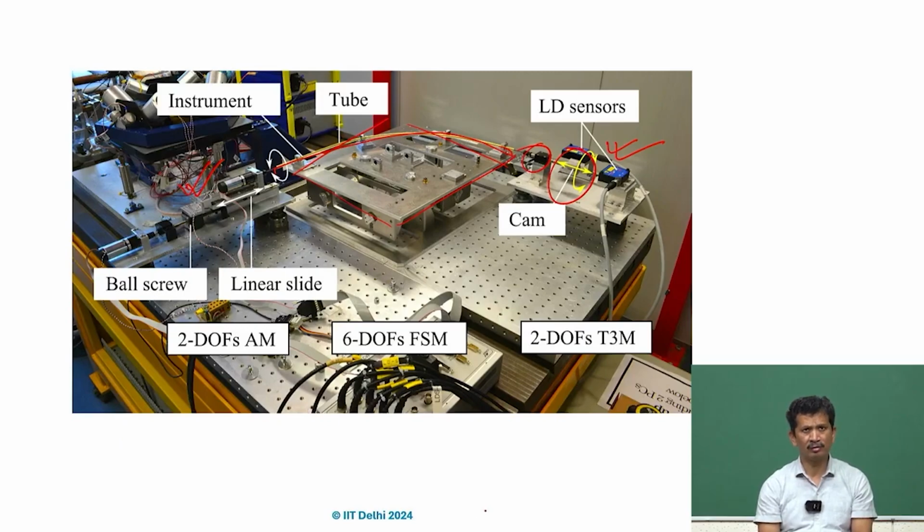It can take a very good load. Of course, if it comes under compression, we have to be aware of the critical buckling load, but if we are able to design it in a way that all the forces are in tension, we can imagine that if we take a steel wire of 1 millimeter diameter and a length of, suppose, 20-30 millimeter, we can do the calculation and check the load bearing capacity. Even the stiffness can be very high because it is EA by L. So, it is all the axial stiffness we are talking about.